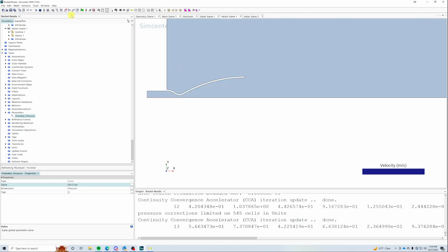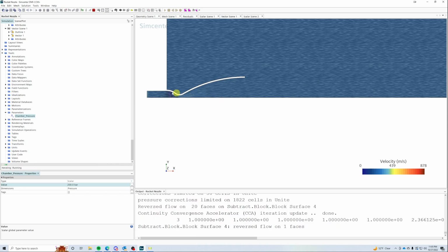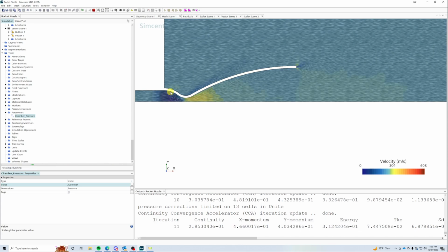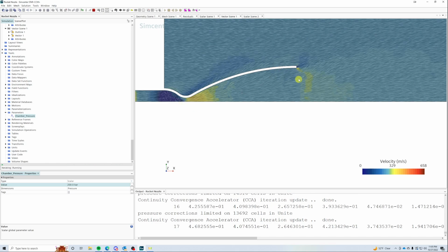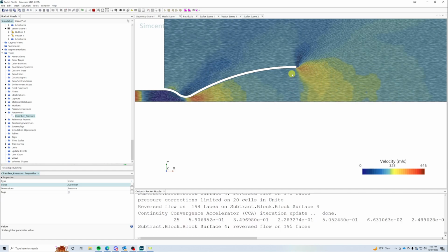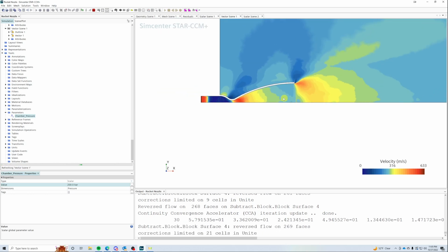The Raptor is supposed to have a chamber pressure of like 300. So we're going to go 200 and see what we get. This is a pretty aggressive area ratio because this is an area ratio of 9 to 9, which is 81. That's a huge area ratio.